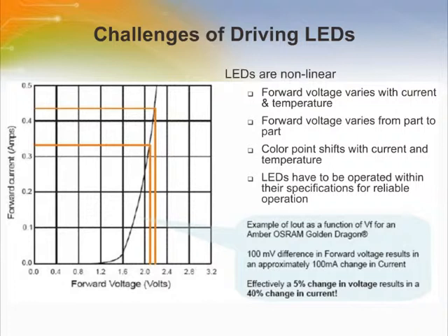The figure illustrates the typical LED forward voltage versus forward current profile. For a given temperature, a small change in forward voltage produces a disproportionately large change in forward current. As LEDs heat up, the forward voltage drops and the current passing through the LED increases. The increased current generates additional heating of the junction. If nothing limits the current, the junction will fail due to the heat. Therefore, constant current drivers are generally recommended for powering LED light sources.